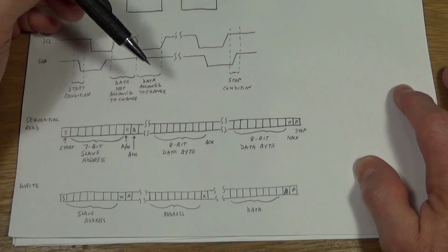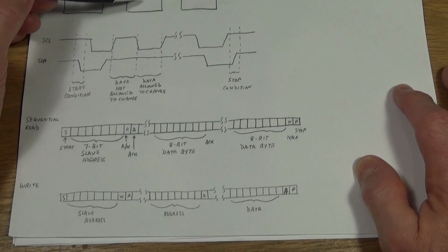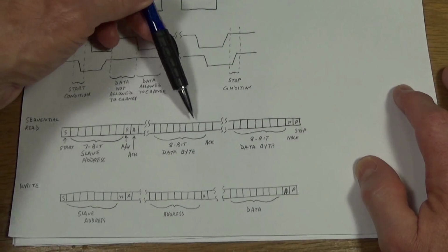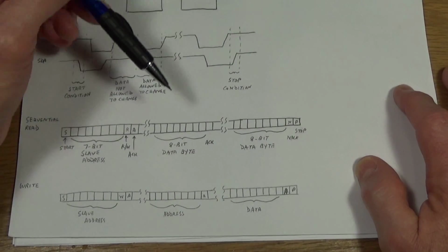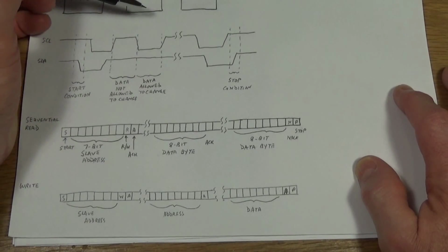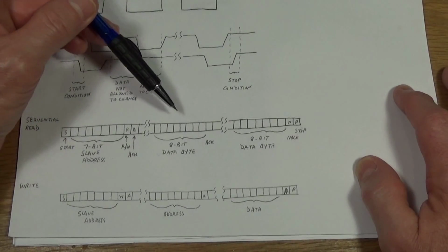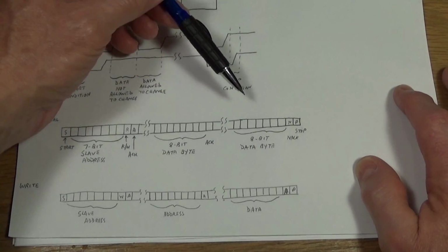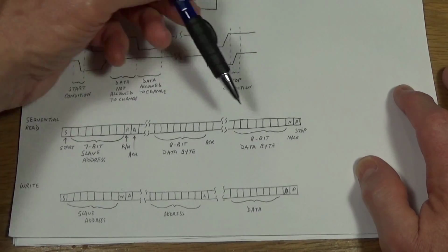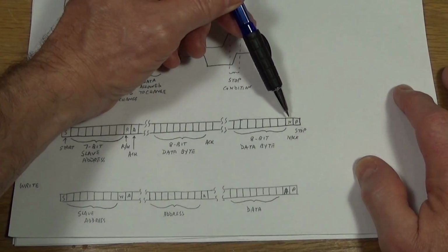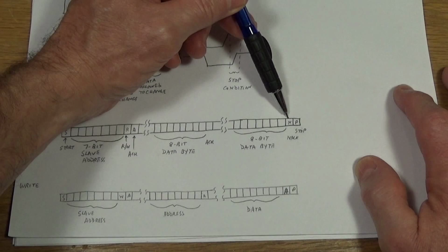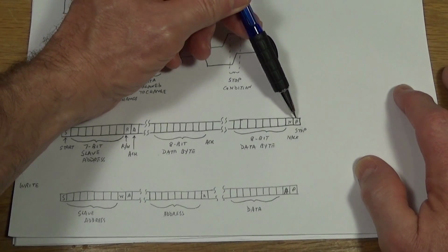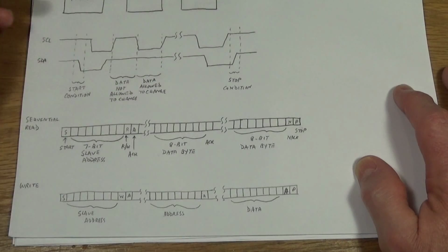it wants. Now, inside each slave device, there's a register pointer, or we can call it an address pointer, that gets set, and I'll show you how to set that in a moment. And so whenever a data byte is read from the slave, it will read from the address pointed to by that pointer, and then that pointer increments to the next address, and the next read will just read from the next address. So this will continue on until the master issues a not acknowledge by allowing the bus to go high on the 9th clock, and then it issues a stop condition to tell the bus and everybody else on it that